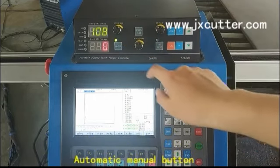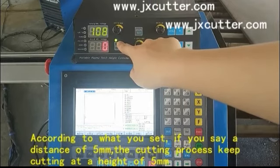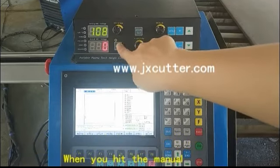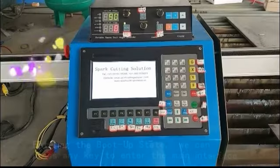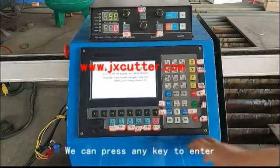Automatic manual button. When the automatic light is on, the arc voltage height controller starts. According to what you set, if you set a distance of 5 mm, the cutting process keeps cutting at a height of 5 mm. When you hit manual, you have to adjust it according to the rising and falling of the cutting torch. At the boot up state, we can press any key to enter the main interface.